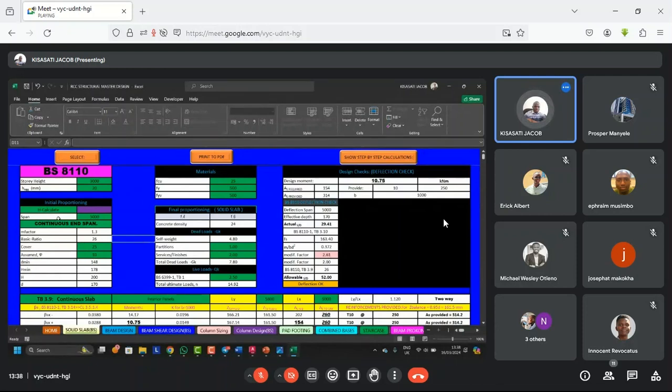Now in Excel, we have two ways, as I said. You will read this: for this point, we have to select the height, select the H calculate, if you like the workbook to perform the initial sizing, the initial proportioning, for you. Initial proportioning is like initial sizing of the slab. Otherwise, the other side, enter the value as per your experience and the nature of the structure.